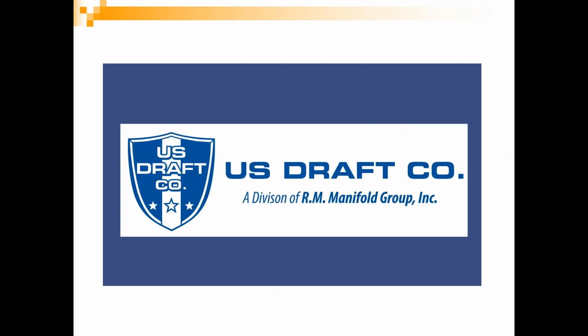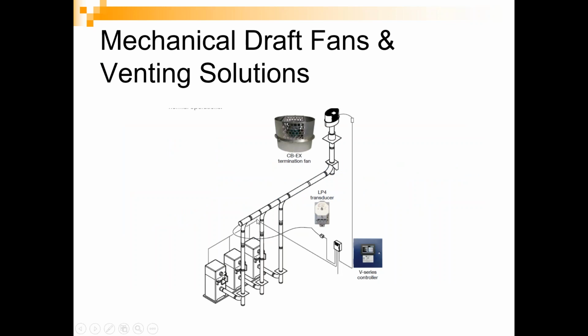When we're talking about gas-fired appliances, one of the other things you have to do is vent it. One of the other products that we represent and have great expertise with is boiler venting. Whether that's the AMCO stack or the HeatFab stack material, we can help design that stack. Or if it needs to be multiple units into a common, we have the US Draft mechanical draft systems, and we can help you design a common venting system where you can vent multiple modulating boilers into a common and use a fan system either at the end or in line. We have multiple configurations for this.